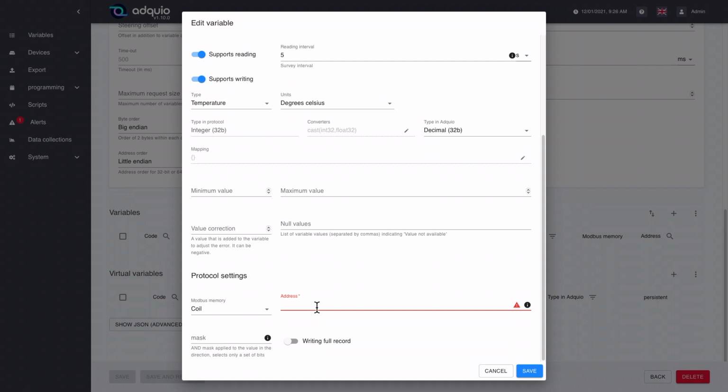You can put an address, dot, and the bit that we want to read, only if they are Boolean variables. You can also put values in hexadecimal. For example, we could put here the address 2, the address 0x20, address 2.13, 0x0f, etc. In any case, these addresses will be given to us in the documentation.